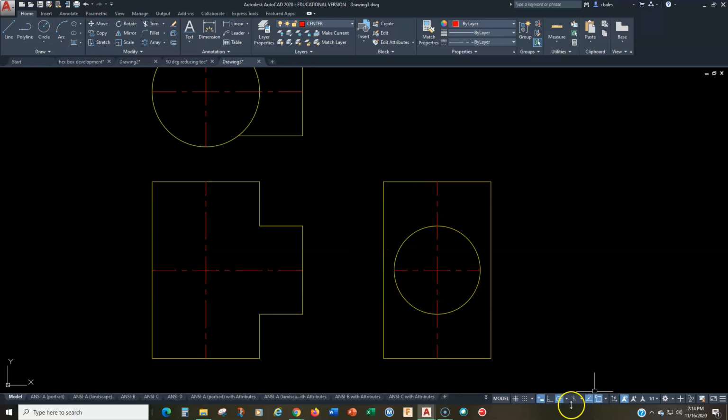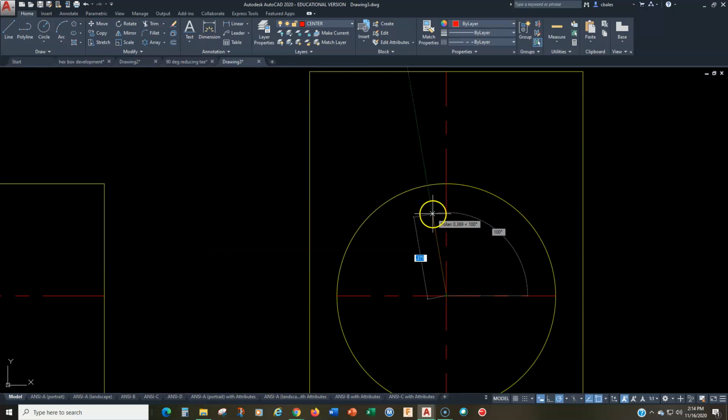I'm going to draw a point at every, let's say every 5 degrees. So I'm going to turn 5 degrees on my polar snap on, and I'm going to draw a line like this. I'm going to draw a line at 5 degrees here. Whoops, I think I missed one. Yep, right there. 5. Right there. Actually, you know what? I think 5 degrees is going to be too much. I'm going to change this to 10 degrees. There's too many lines there. So let's go 10.